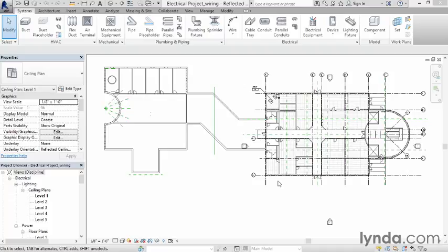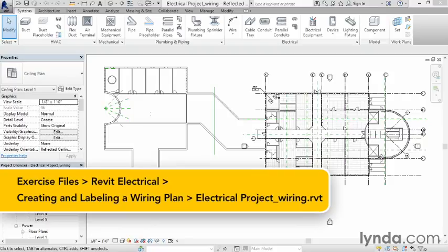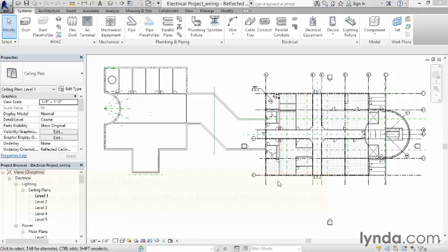Some companies show wiring, while some don't. Even if you don't, this video is a good way to see your systems in action. Because Revit knows you have a system in place, it knows how to automatically draw in your wiring. We can draw in the wiring as if we were sketching arcs as well.